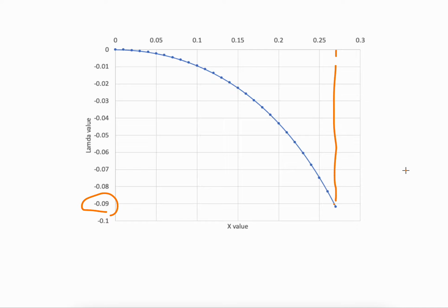Again, the calculation is not straightforward. It is not just that you substitute the value and get the final answer, because at this stage all the evaluation of the boundary layer is actually conducted by curve fitting, as I showed you in the previous graph. Previous researchers did a lot of analytical and experimental work, and they came out with the equation by curve fitting. So it is not just a simple equation that comes from derivation.